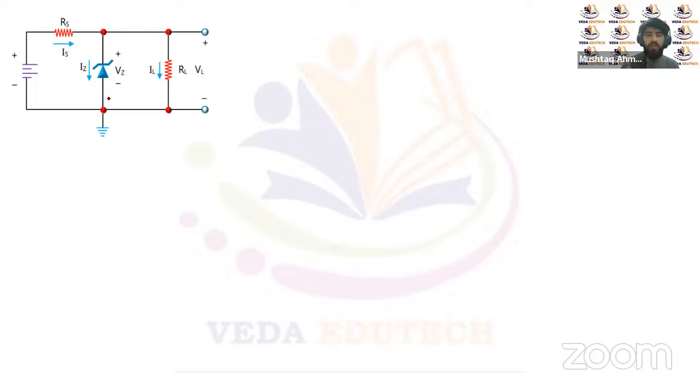So any resistor, load, capacitor, or inductor connected directly to this Zener diode will have a constant voltage equal to the breakdown voltage of the Zener diode. That's the reason we say that the Zener diode is used as a voltage regulator.